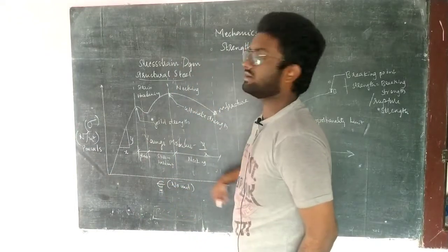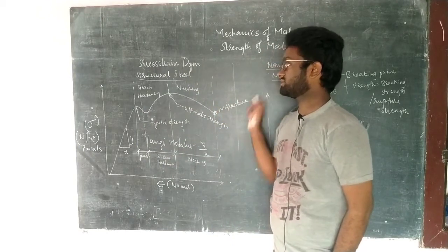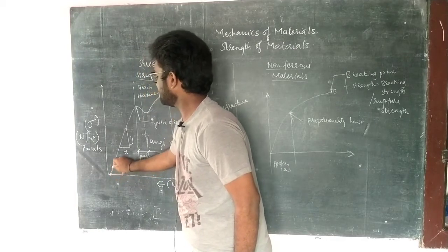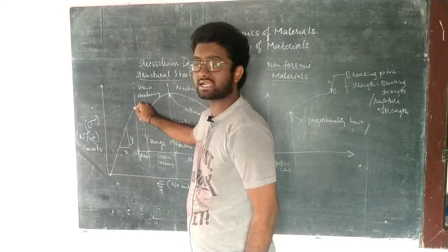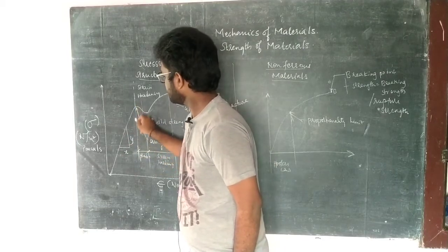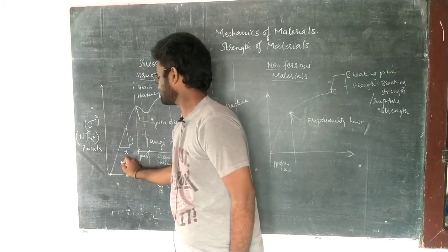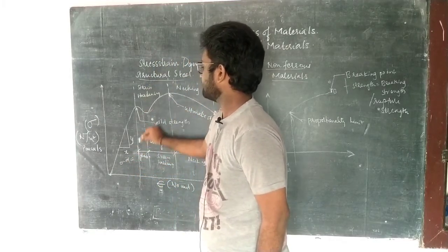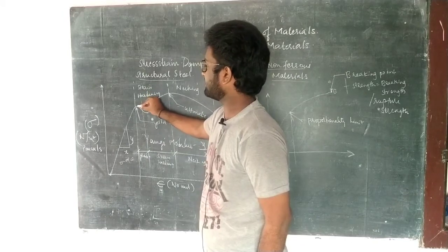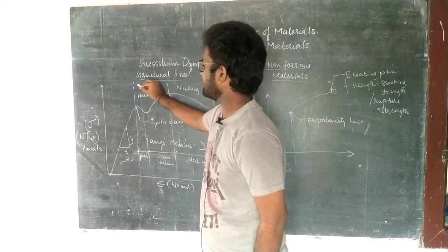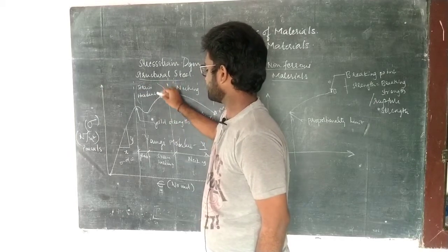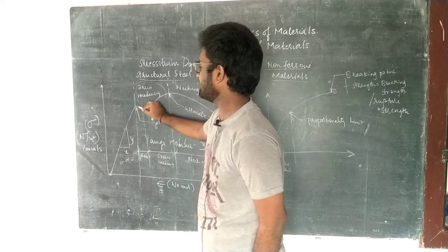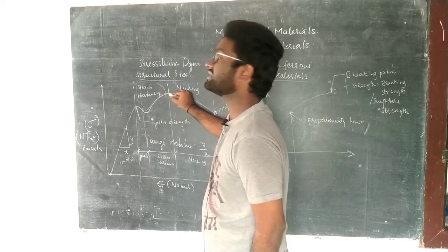You can see this particular diagram, it is the stress strain diagram for structural steel, wherein initially from this point there is a linear increment. The stress is directly proportional to strain, so here there is obeying of Hooke's law. Later this zone is called the plastic zone, where there is a slight reduction and then strain hardening takes place, which can also be called plastic plus strain hardening. That means initially there is a mild decrease and again there is a maximum increase.